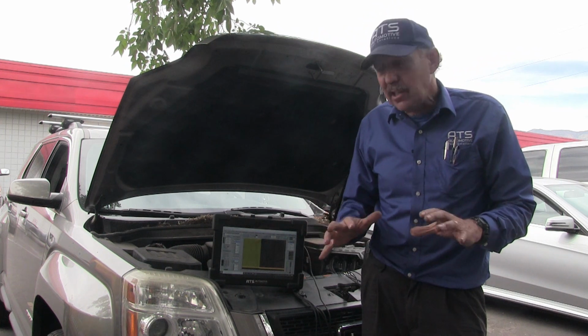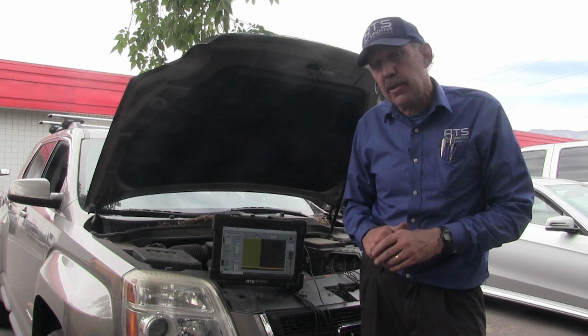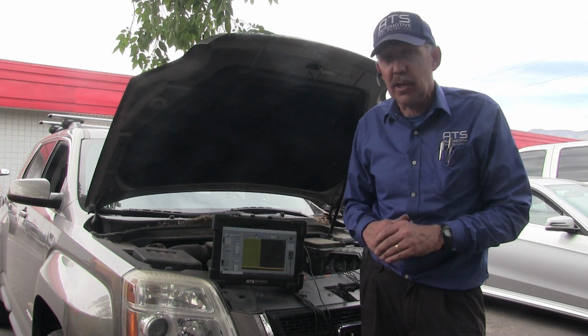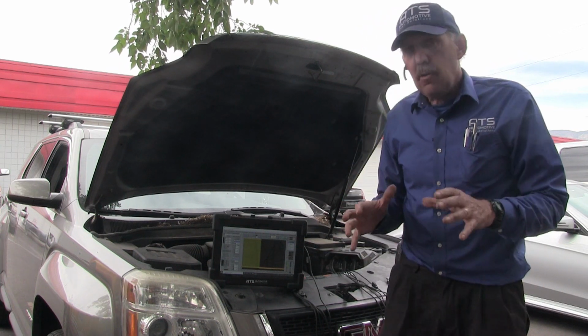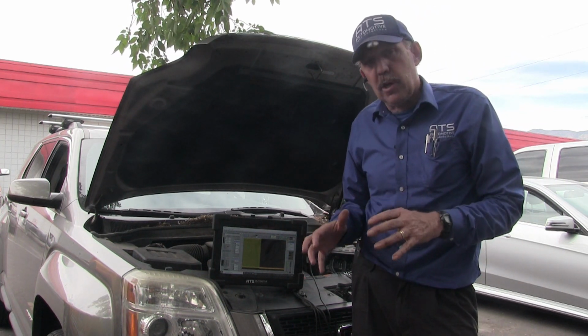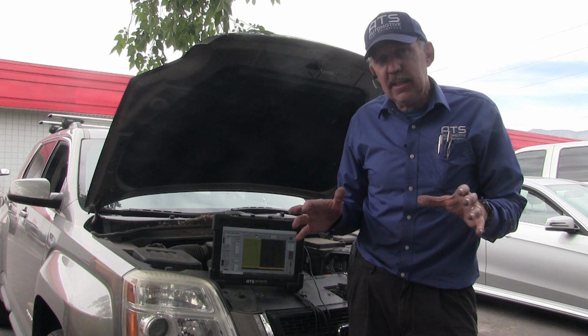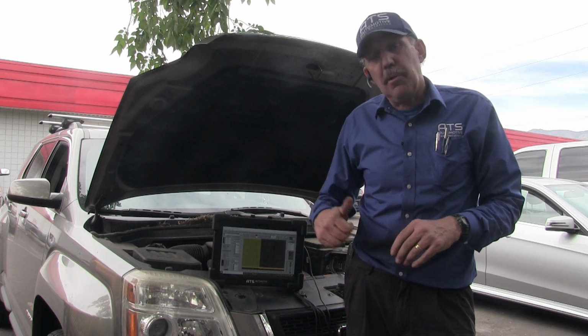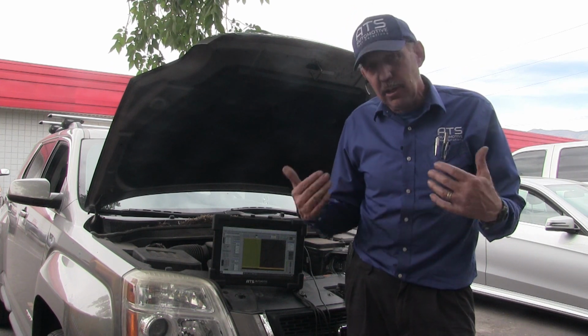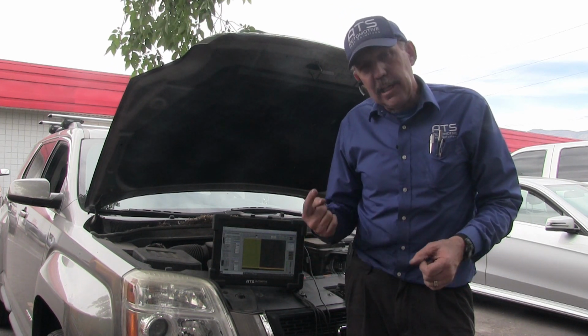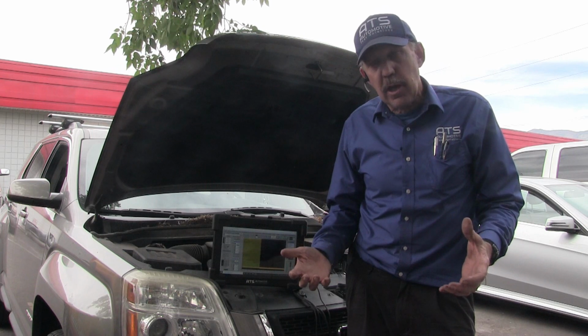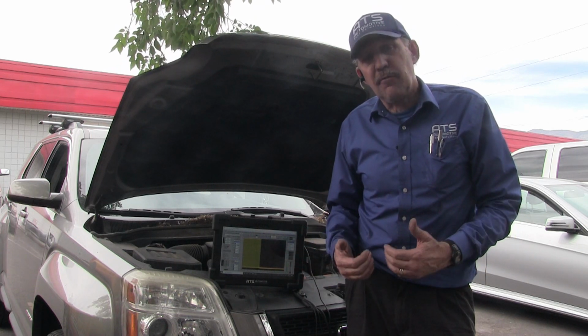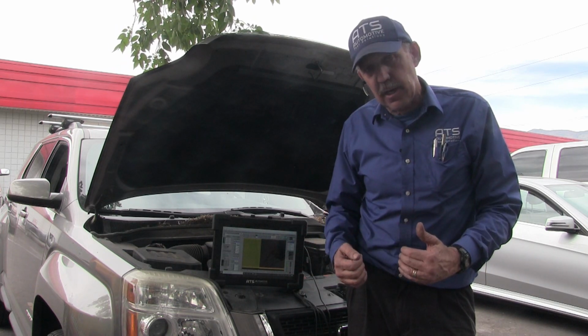Now before I release anything, I want to show you guys one other test that you need to know about. If you have a problem with fuel control, one of the easiest things you can do is use a 5-gas analyzer on it. You put a 5-gas in the tailpipe and you look at the lambda. If the lambda is 1, or stoichiometric, that means that the fuel control system is functioning.